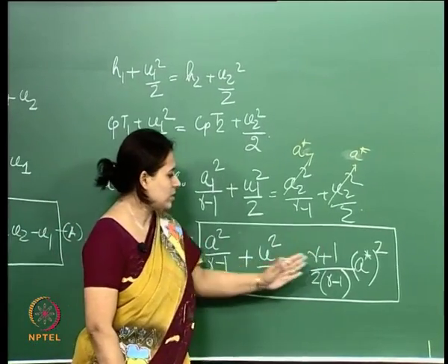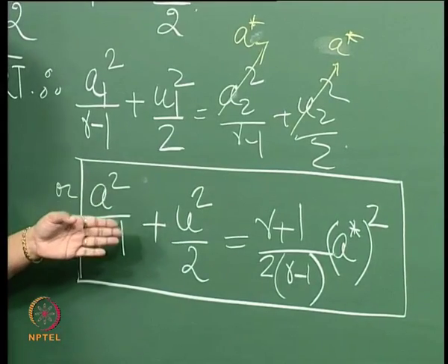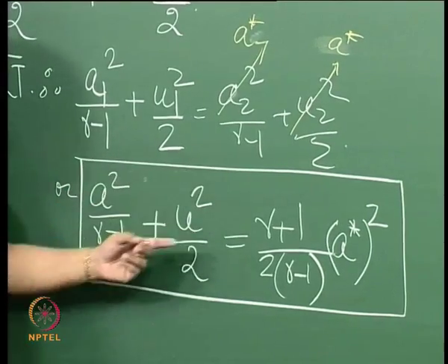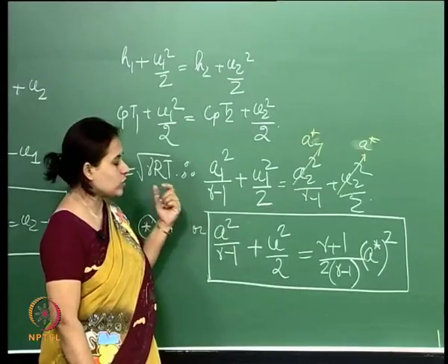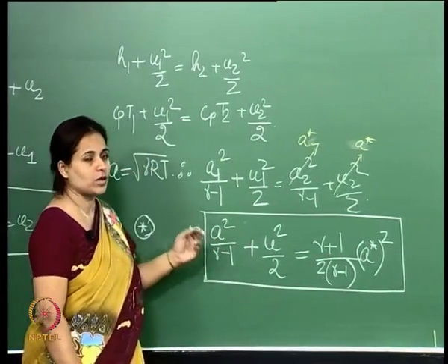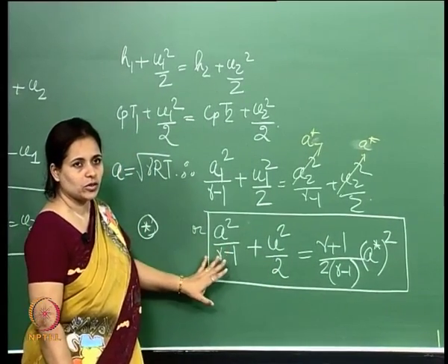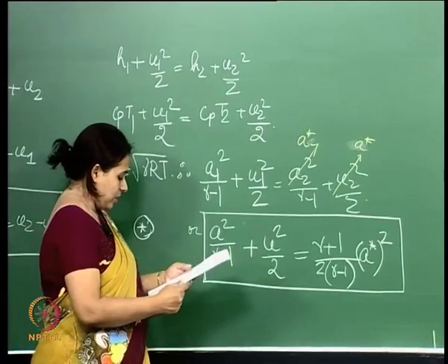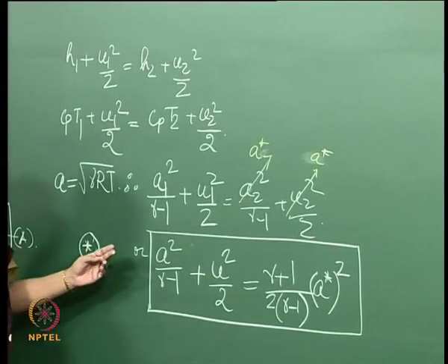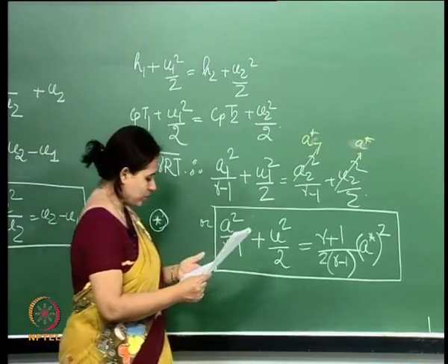Then this is the relationship, and nothing here is telling us whether the velocity there is supersonic or subsonic. It could be anything, because if it is supersonic I can slow it down to the sonic zone, and if it is subsonic we can speed it up to the sonic zone. So, nothing here gives me any clues as to the incoming Mach number. Now let us write this for two zones, and what we will get is this.